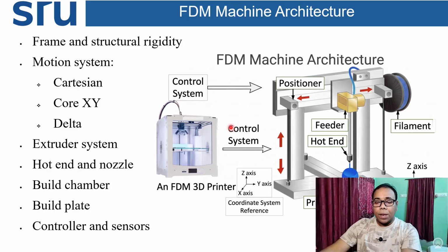Now this is one printing machine. In that printing machine, the inside structure will look like this. Here x motion could be in this direction, so this stage will move for the x direction movement. Similarly, this stage can move in this direction for y direction motion. Similarly, this stage can move up and down for the z direction. The x and y directions are used for giving the particular contour motion on that layer. Similarly, z motion is given for the different heights. So moving from one layer to another layer, the z motion will be required.